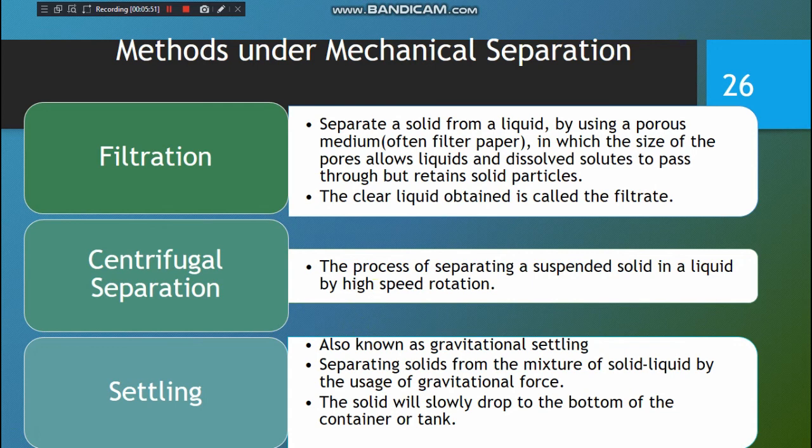So centrifugal filtration is the second type of centrifugal separation process. It is similar to ordinary filtration, where a bed or cake of solid builds up on the screen, but centrifugal force is used to cause the flow instead of pressure difference.